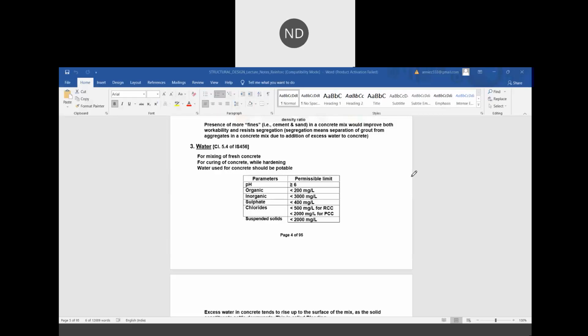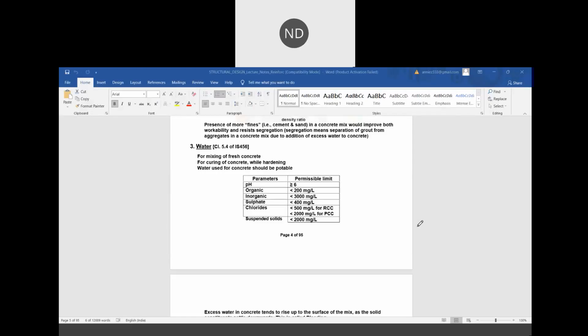The sample shall be stored in a clean container, previously rinsed out with similar water. Average 28 days compressive strength of at least 3 150 mm concrete cubes prepared with water proposed to be used shall not be less than 90% of the average strength of 3 similar cubes prepared with distilled water.